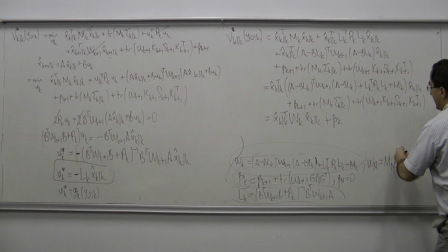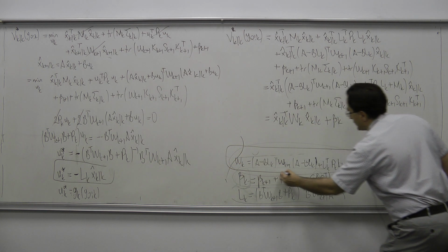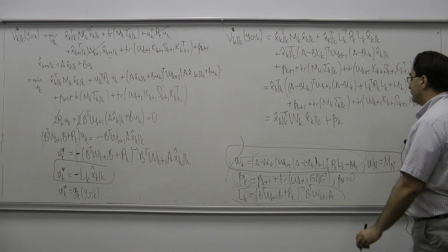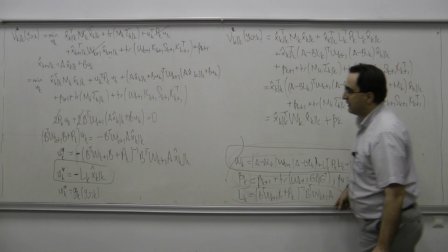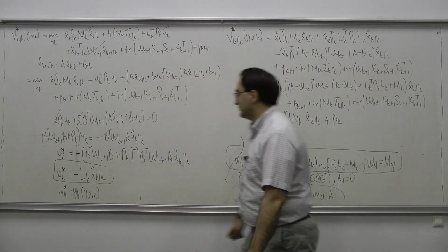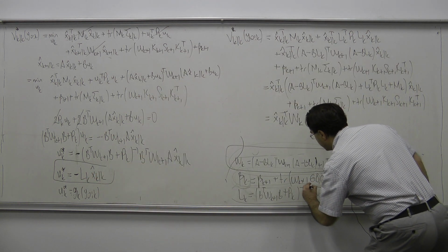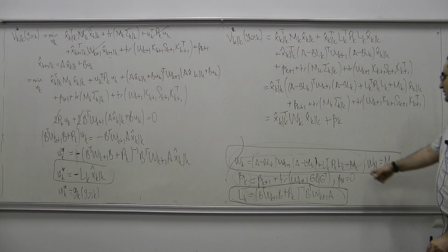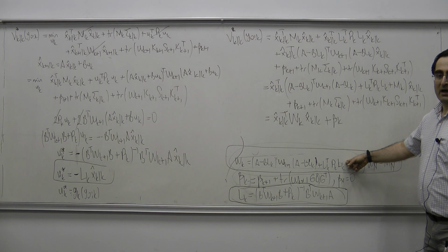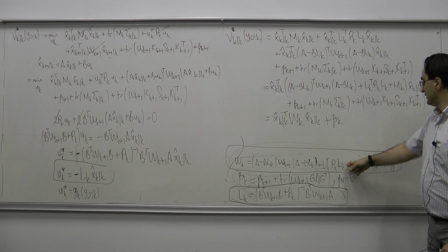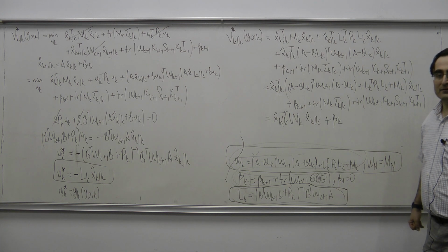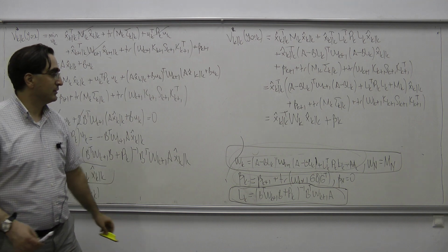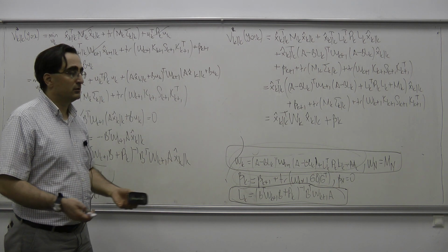So I have exactly the same backwards Wk recursion. And furthermore, I have exactly the same feedback gain formula. So W's remain the same as in the complete information case, and Lk's remained the same as in the complete information case. What changed here?